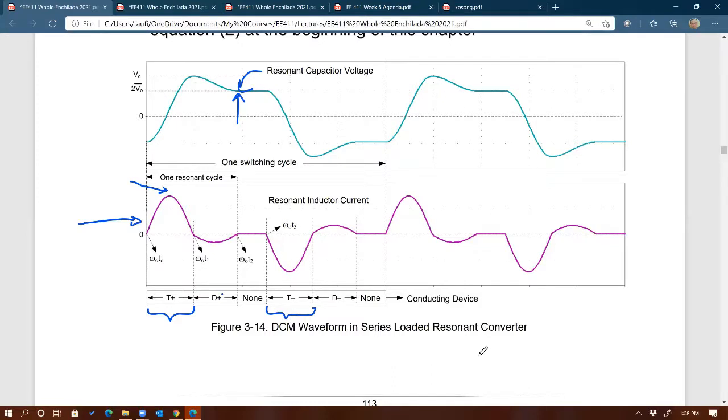What is a semi-controllable switch? We tell the switch when to turn on, but then the switch will turn off by itself at zero current, just like a diode. So can we use a semi-controllable switch such as thyristors for this? What is the answer? Yes. Why? Because we just need to tell it to turn on, it stays on until it becomes reverse biased, and then we don't have to worry about turning it off again.